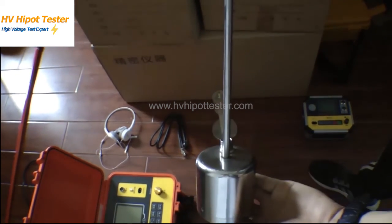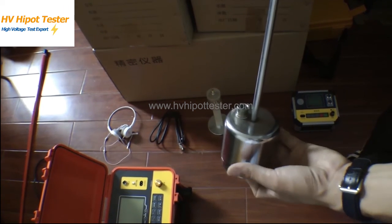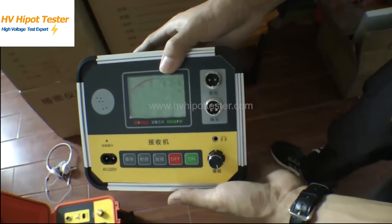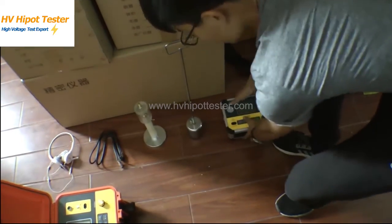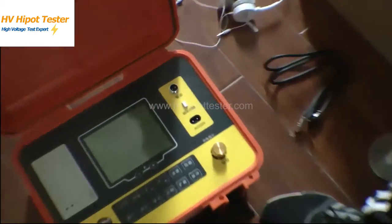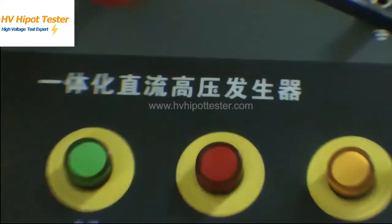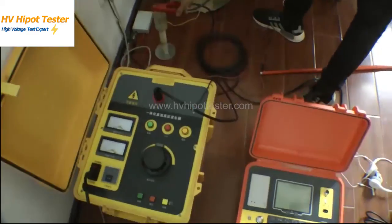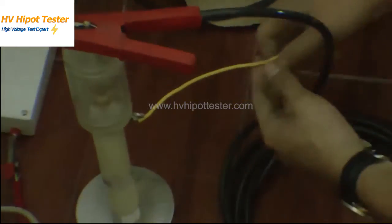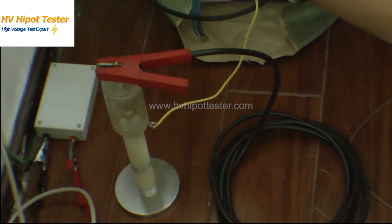Shock sensor. The receiver. The fault distance detector. High voltage generator. Connect high voltage output terminal to the top of sphere gap. The terminal at the downside of sphere gap connects to the fault cable. Steel armor of cables connect to ground.